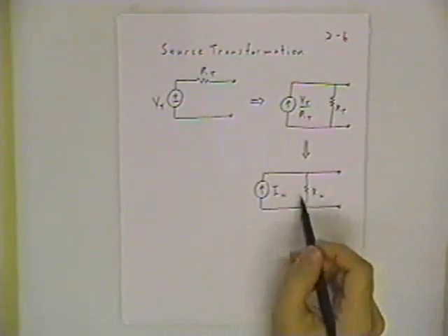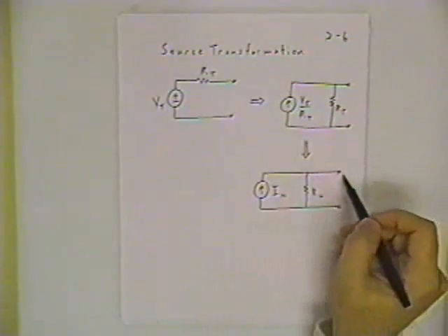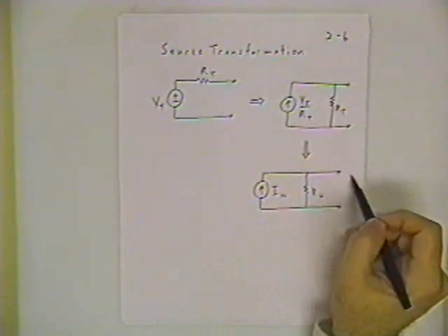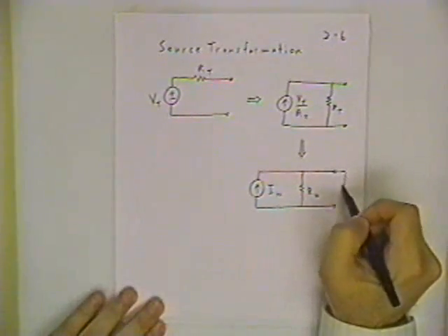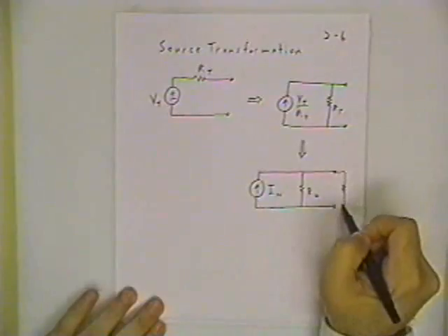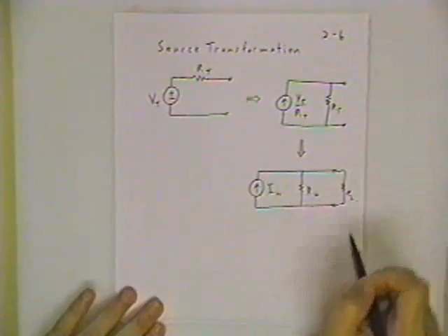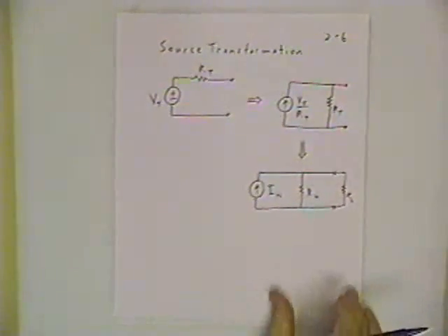Well, this gives us one possible way of solving problems where all you're really interested in is the current or voltage for a particular load resistor. Once you have the equivalent network, then you can just reattach your load and proceed with the calculation. Another practical consequence is that you can figure out how to maximize power transfer from an active network into a load. This has application in audio technology.